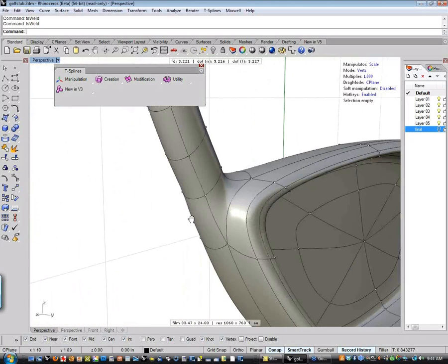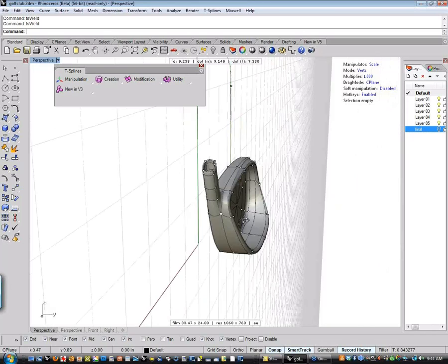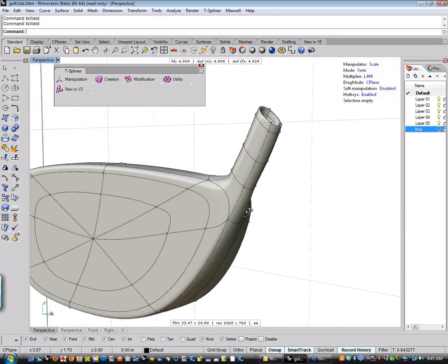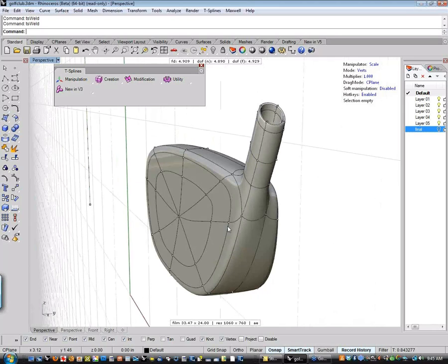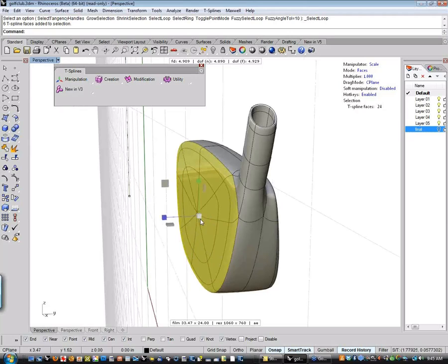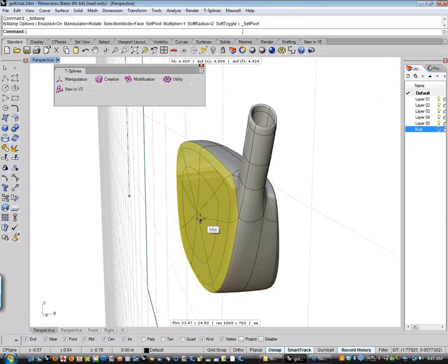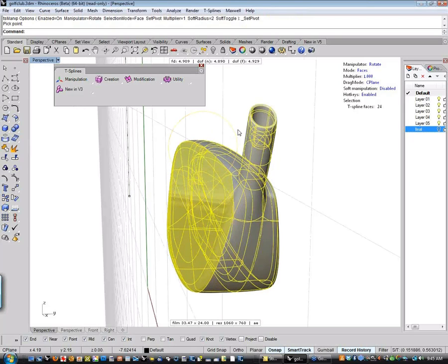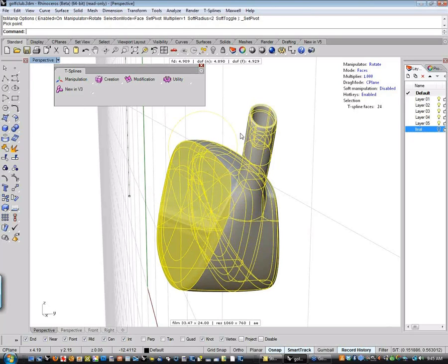So now this club is essentially done, and obviously it's not something that you could play with because the offset's all crazy and stuff like that, but if I wanted to change the loft on this thing, I could pick these faces, go to the rotate manipulator, I can change where the manipulator goes from, and I can just change it from a 3-iron to a 9-iron.